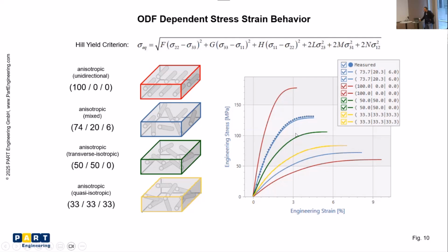And that leads, of course, to a whole different nonlinear material behavior, if you look at this, and of course for different directions as well. So what's displayed here is always in the main direction and perpendicular to it. So for this blue, very general one, you have this stress-strain performance in the main direction, if you make a tensile test, and this behavior would be perpendicular to it.